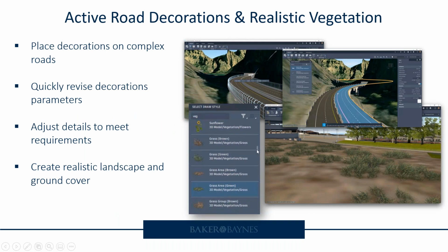So what I mean by that is this, okay? Before, when we used Infraworks, we normally attached, or let's say, for example, we inserted a retaining wall in the center, or a barrier, like you can see on your screen right here. And when we added it along a component, we had to wait until it regenerated, and if it was orientated or facing the wrong direction, we had to enter the angle again, and then wait for it to regenerate, and then see if it was correct. It took a lot of time, especially if you had quite a long roadway or quite a huge model, and it could become very frustrating.